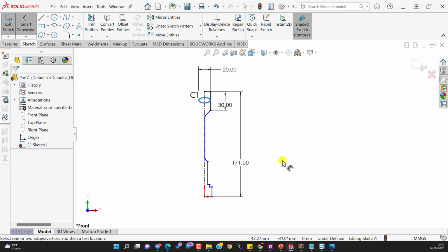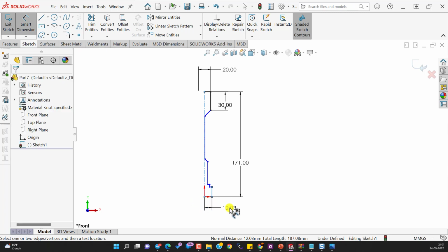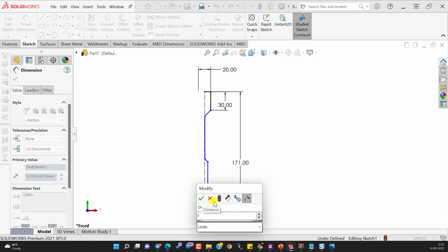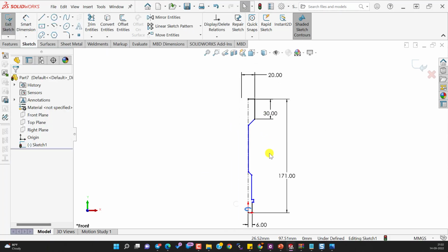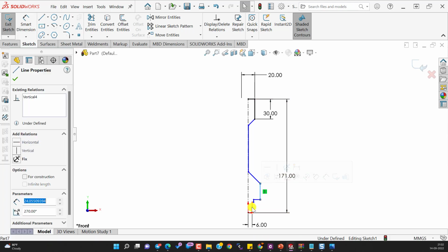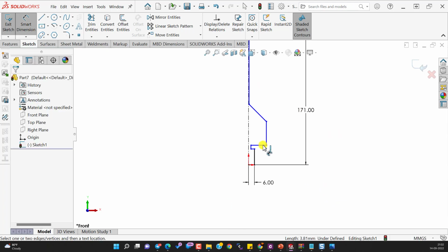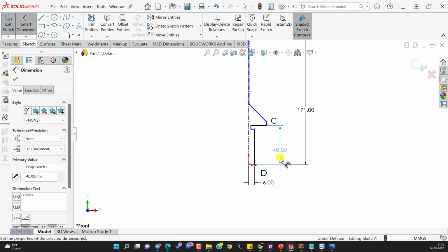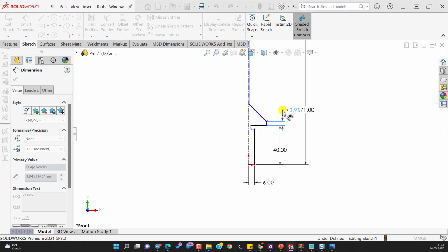Give the diameter of circle C1 equal to 20 mm. Now, give the radius of the circle C2 equal to 6 mm. Just tweak the current sketch into the required shape. And give the height of CD equal to 40 mm. Establish 5 mm as the height of EC.